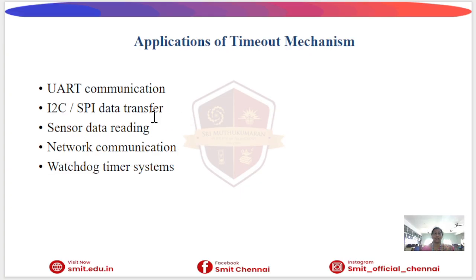The applications of the timeout mechanism are UART communication, I2C, SPI data transfer, sensor reading, network communication, and watchdog systems. If the system hangs, the watchdog resets the microcontroller. So it is a very important concept in the industry.